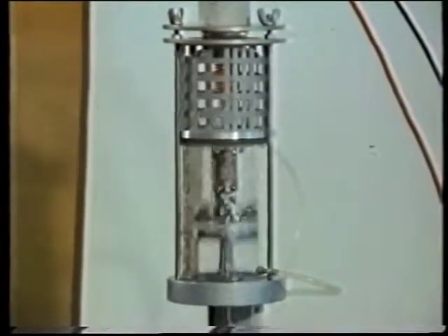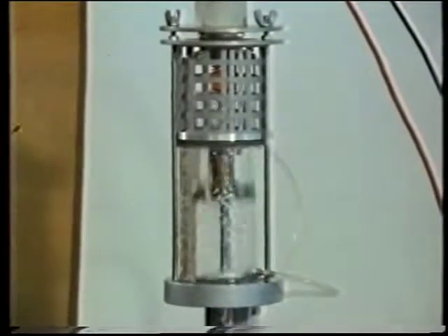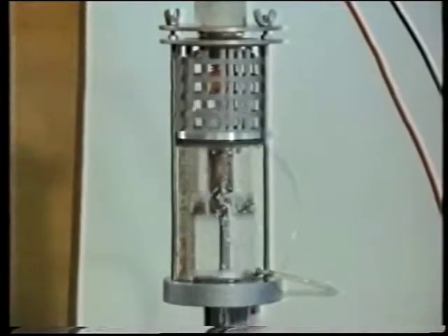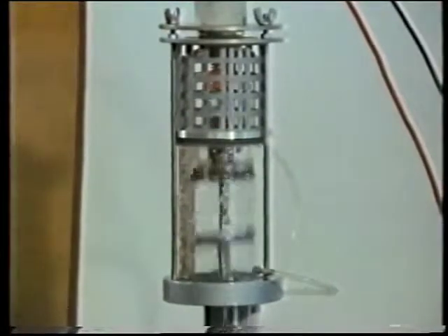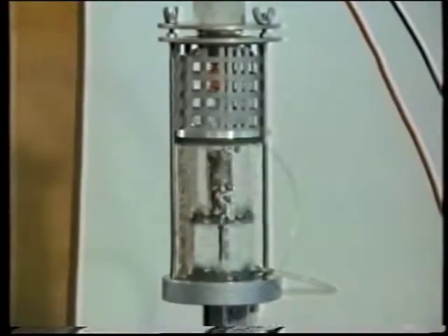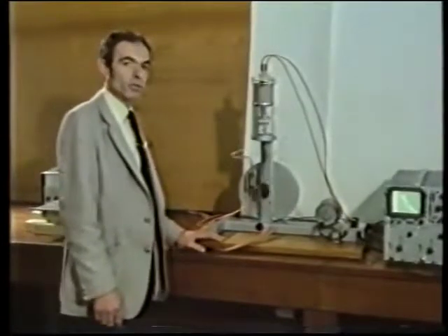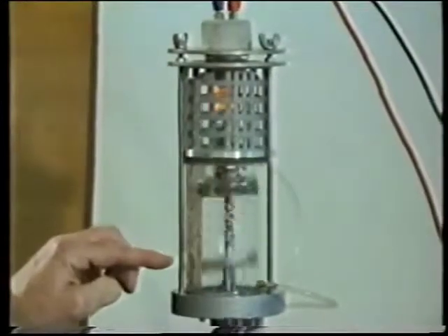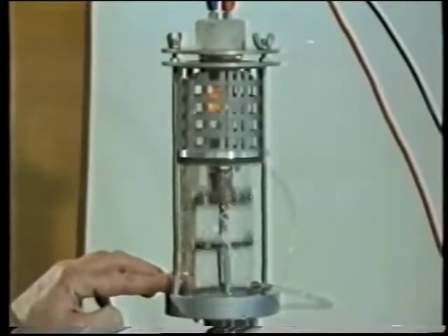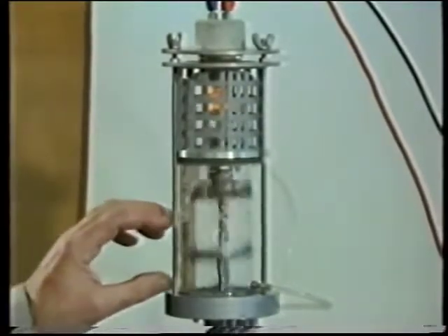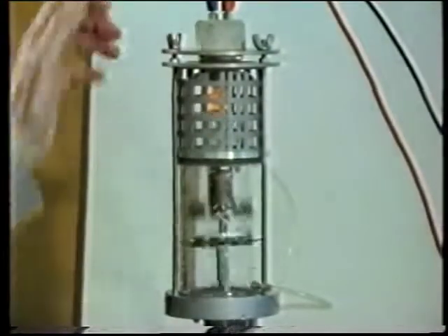Now, the Carnot cycle is an idealized engine, but this is a real engine, also using a closed mass of gas as a working fluid. It's called a Stirling engine, and at Reading University, Dr. Graham Rice is interested in it, both for teaching and for applications. The Stirling engine converts thermal energy into mechanical energy. Gas is kept hot during expansion and cold during compression. The engine has the following basic components: a cylinder containing a working piston or power piston, and a displacer which divides the engine into a hot space and a cold space. The engine is heated at the top and cooled at the bottom.